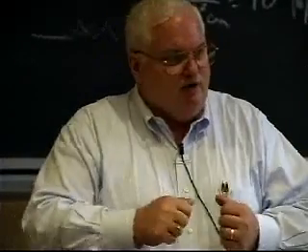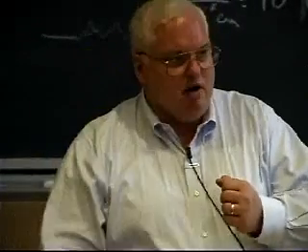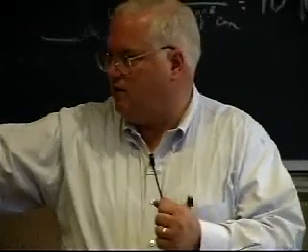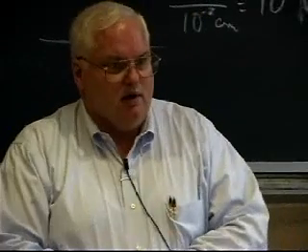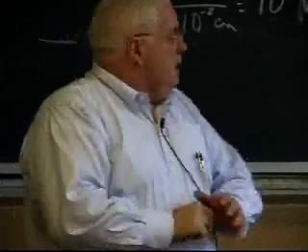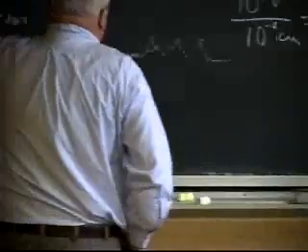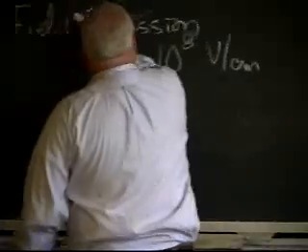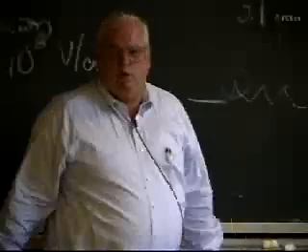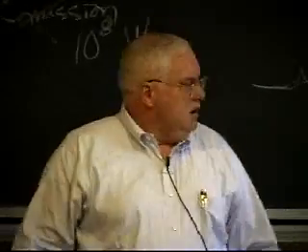At 10 to the 8th volts per centimeter, I actually lower that barrier enough, I actually do get tunneling of electrons right out of my metal into free space. But Paschen breakdown was just an example of that, but you still need thousands of volts. So again, the welding handbook is wrong. Okay?